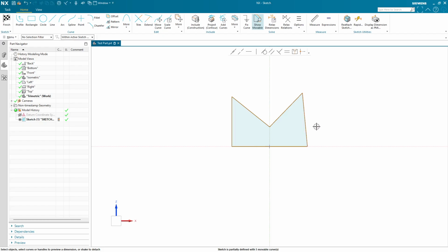On this side, let's say we also want 90 degrees. Let's do that with an angle constraint. So when you click two lines, it will give you possible relations between them or possible dimensions between them. And in this case, the only dimension possible between these two lines is an angle. And so in green, it is saying, hey, just a heads up, these are about 84.6 degrees, just to let you know. But if I click away, it goes away.